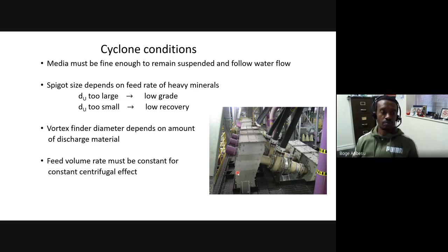And also you should not vary the feed rate. So feed coming from here should be of reasonable flow rate, shouldn't vary considerably. If you vary it, you vary the hydrodynamics inside the cyclone. That again will ruin the consistency of the product that you're making as well.